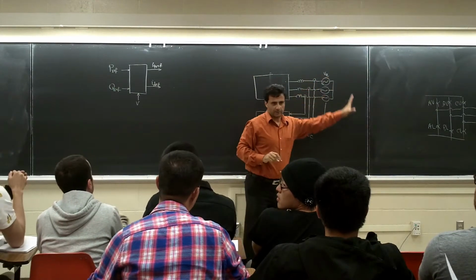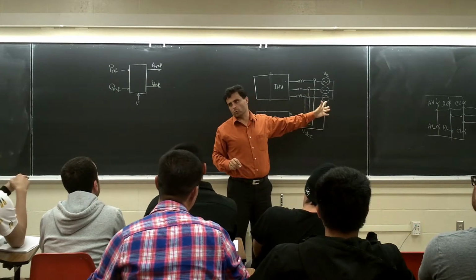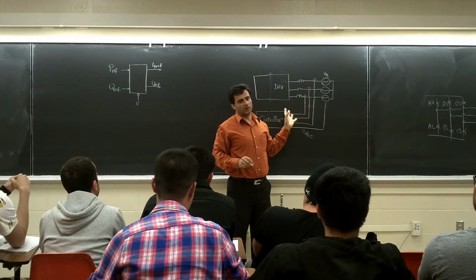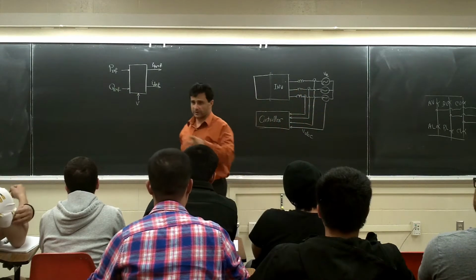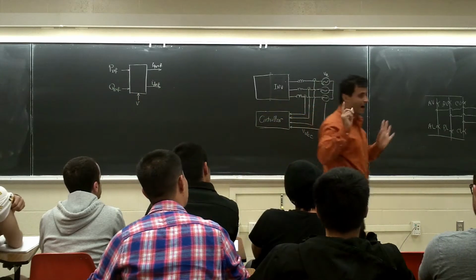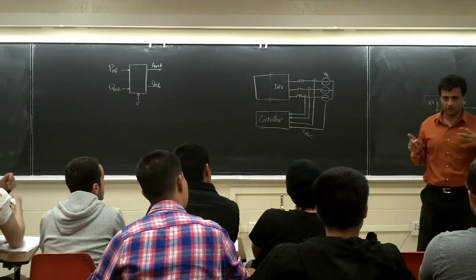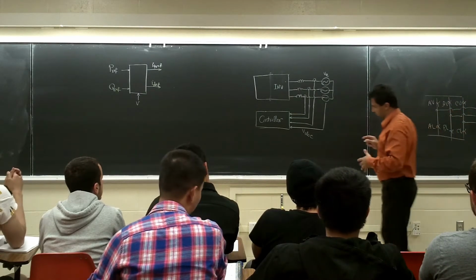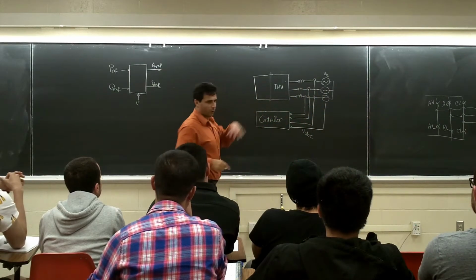It has all the sensing. It could be temperature. The signals we are using only for control, I put here. But there are lots of fault signals. For example, they measure the temperature of the case of that IGBT. If it goes above a limit, you have to shut down your circuit. You don't want to let it run because it's going to kill your inverter, right? There are tons of protections. We don't talk about those things. But it shows the current and voltage here.